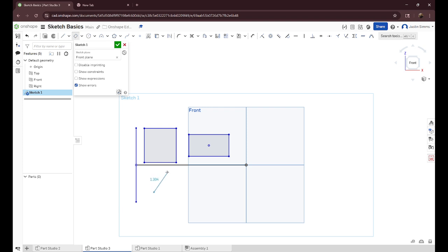Aligned rectangle, it's the only one that's kind of different, and it's nice if you're working at an angle because you select the primary angle with 2 points, and then that'll make your width or length, or whatever you want to call it, and then the other dimension is made with a third point, so it's a little bit more customizable.